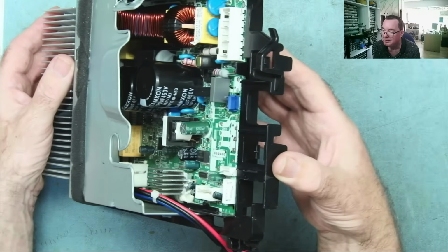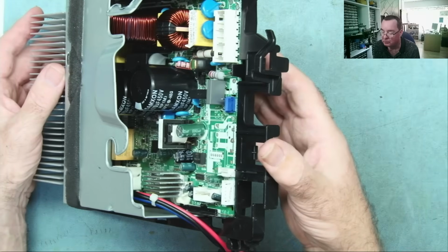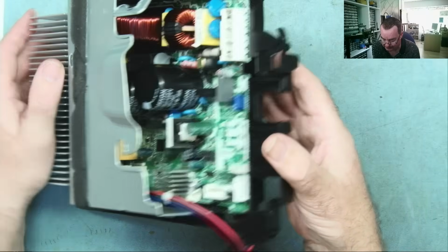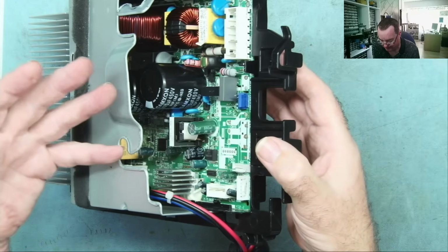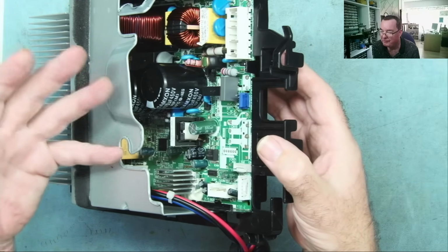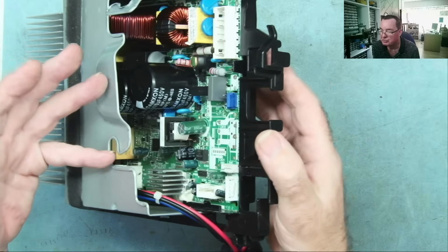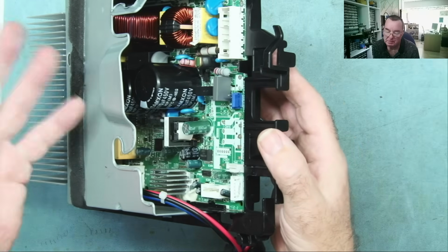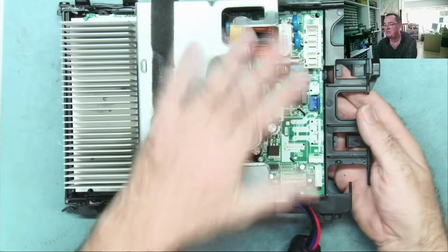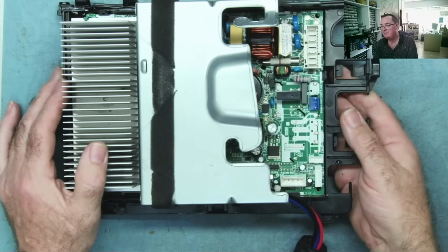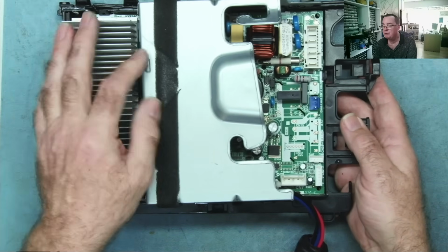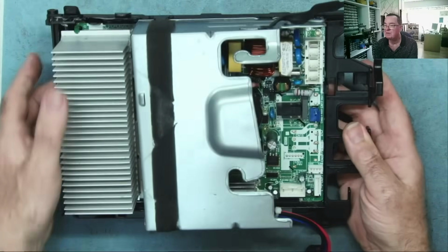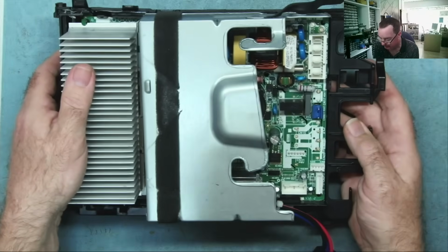One of the problems supposedly that causes these sort of errors is a corrupted EEPROM, but I have no idea if I need the right file contents or if I can actually just erase it and put a blank one in. I tried that on a very similar board to this. It still powers up with its relays, but that owner is not on the island at the moment, so I can't honestly say if it made any difference.